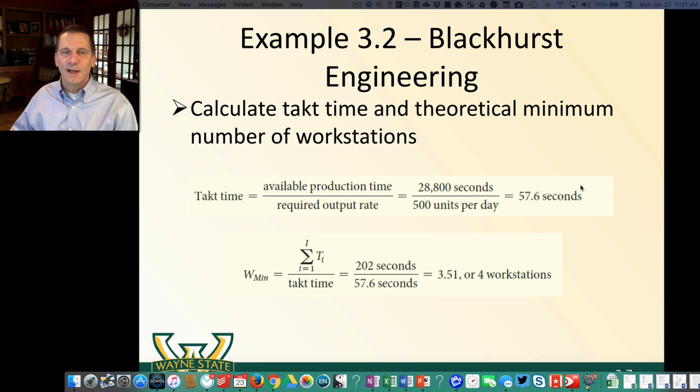It doesn't consider a lot of real-world stuff like taking breaks, going to lunch, downtime for equipment and so forth. So this is a very simple and optimistic takt time. In reality, if we built our business around that, we'd be asking for trouble, wouldn't we? Because things do happen, and lines don't run 100% efficient. You'd probably take that figure and divide it by 0.85 or some factor to say, no, we can't assume 100% efficiency at our takt time. But for this simple model, there is our takt time.